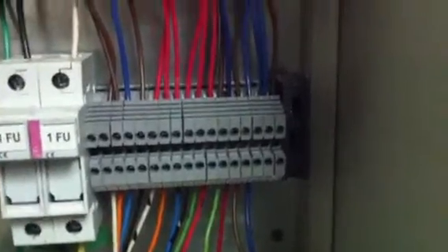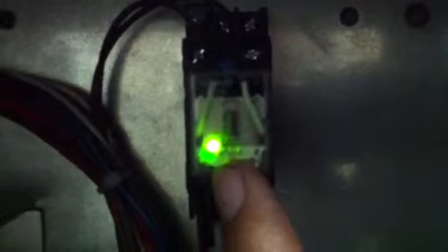Another feature of this is that the fire sensors are connected to this safety relay, and this is continually monitoring. So in case one of those sensors goes bad, this relay will come down, will go off, and will tell you that you have a problem in your system. So this is going to be always on, so we know all the things are working properly.